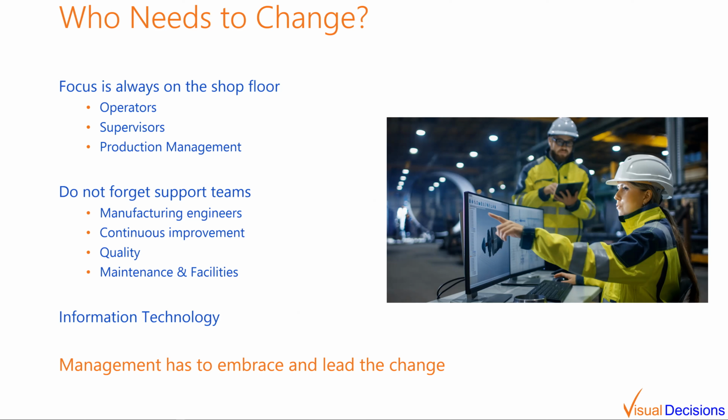My quality department needs to utilize this data to identify the root causes for variation in the process, and looking at things like vibration and sound analysis and how that correlates to the quality issues that I'm seeing in my SPC charting and so forth. And then maintenance and facilities, using this information to keep the equipment running much more effectively through techniques like predictive maintenance or condition-based monitoring, instead of just doing reactive maintenance in the future.